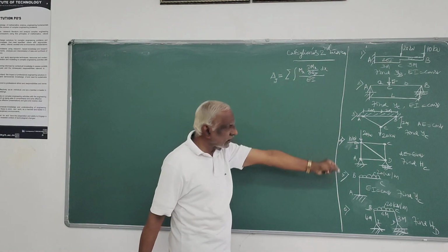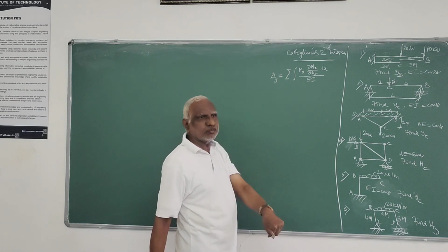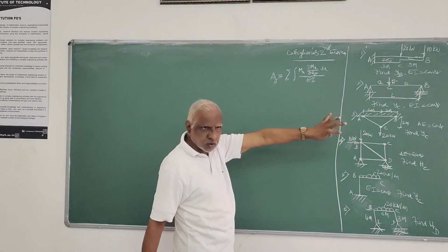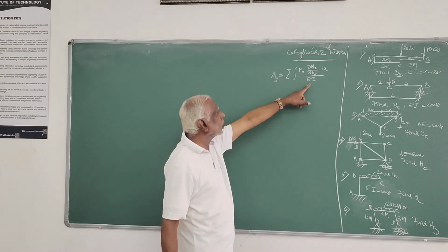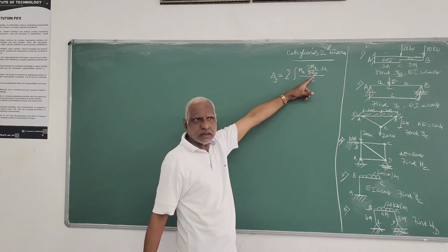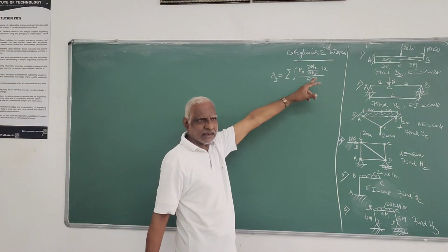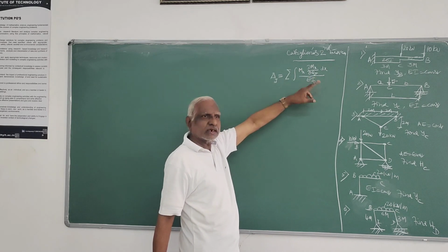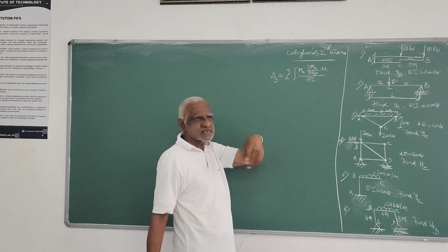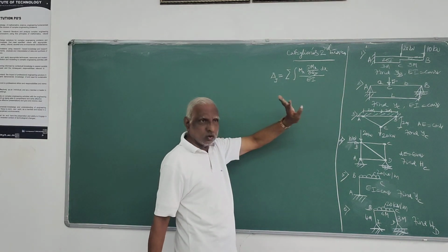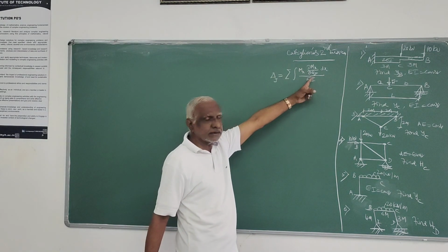If it is vertical deflection, you apply a vertical force. If a slope or rotation is to be determined, you have to apply a moment as the load. It is an imaginary type of load. So that value you can put as 0 afterwards, if there is no load given in the problem along that coordinate.